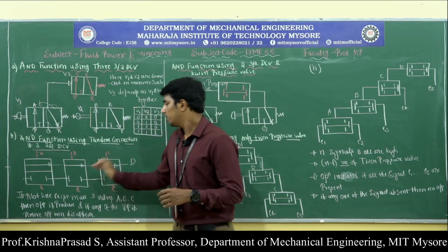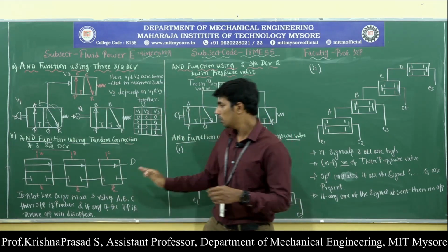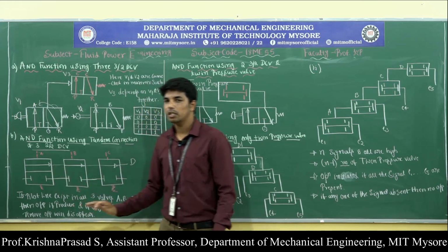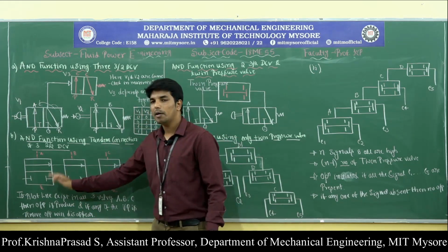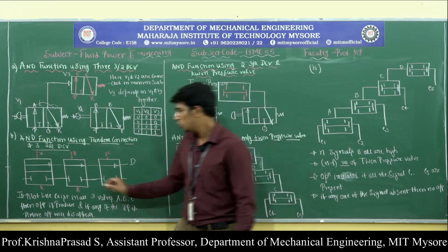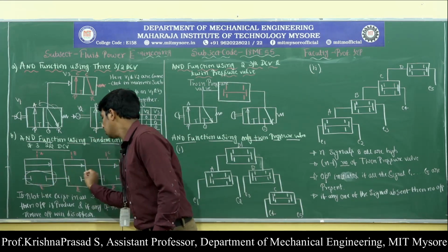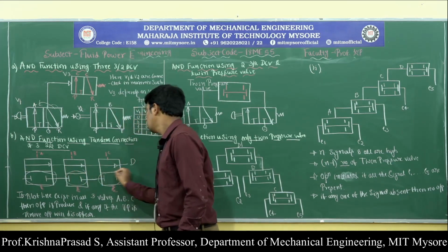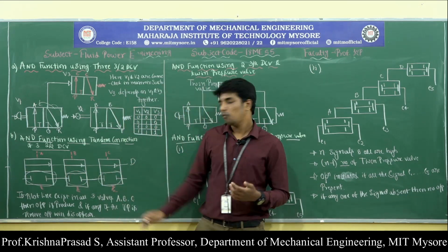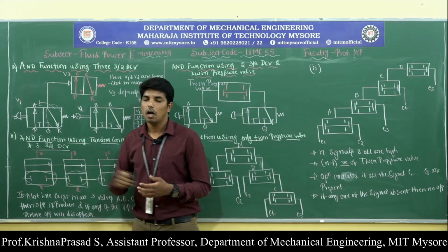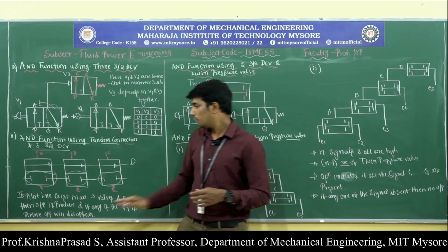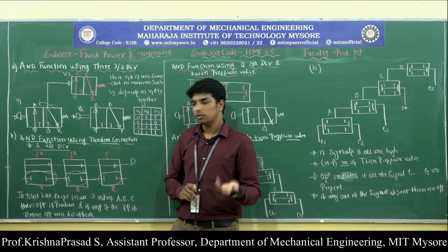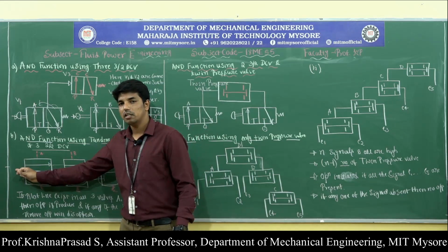So, a very important thing: initially, or during the normal condition, all the 2 by 2 direction control valves are in the normally closed condition. So initially they are all in the normally closed condition. Hence no pressurized air will flow from the inlet port to the outlet port. If the push button is operated for the first direction control valve, then it will send the signal to